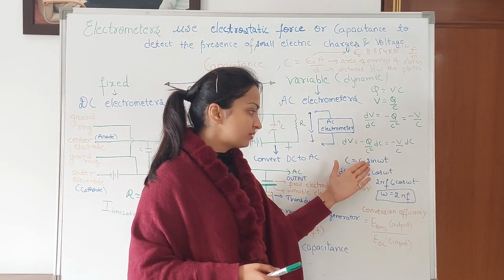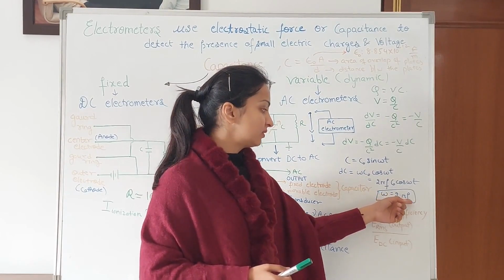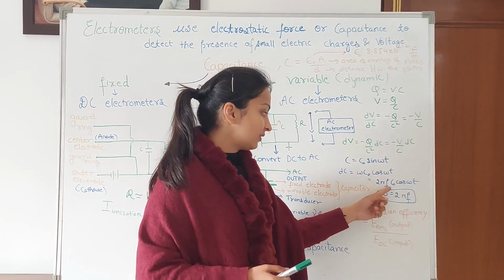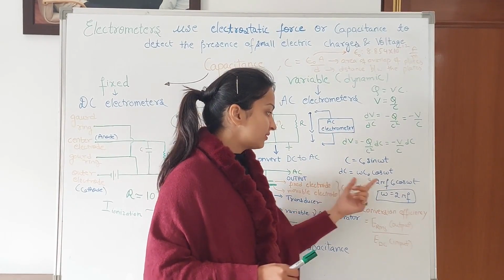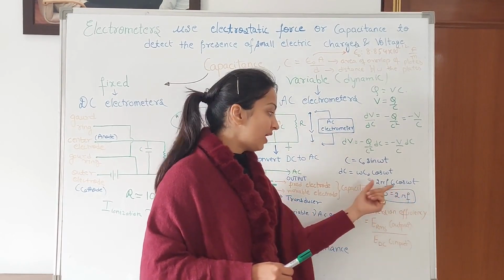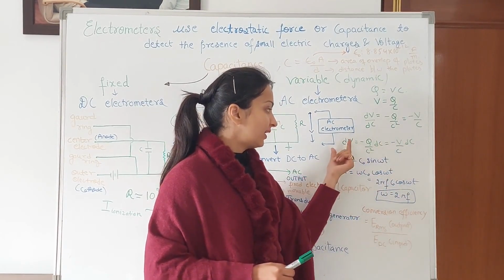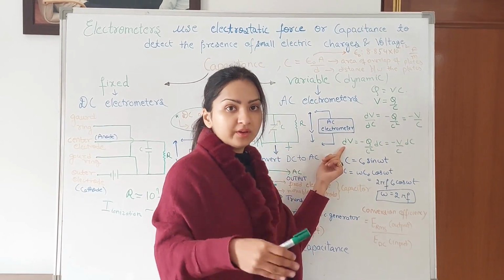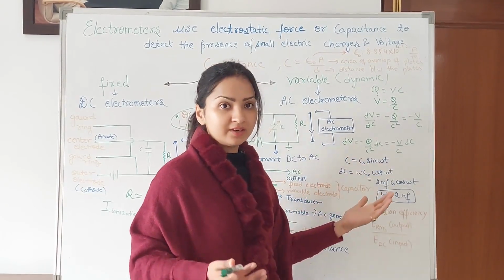This change in the value of capacitance will give you this expression. Simply we have differentiated this expression. Now this angular frequency is related to frequency via this relation, so instead of omega, I can write 2 pi f. Now this value of dC comprises this cos omega t term and this frequency. If I put this value over here, I can clearly say that my output voltage is now varying periodically with time and uniformly. So it is a sinusoidal type of variation.